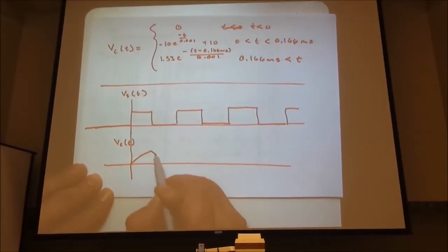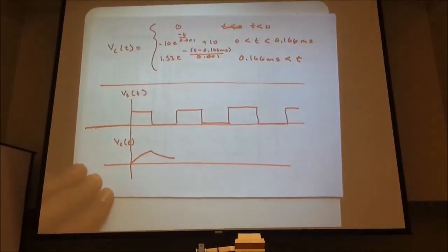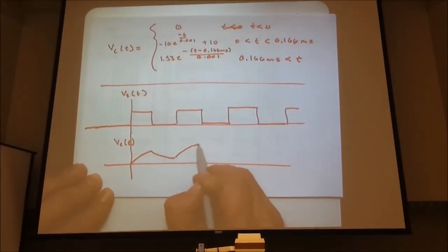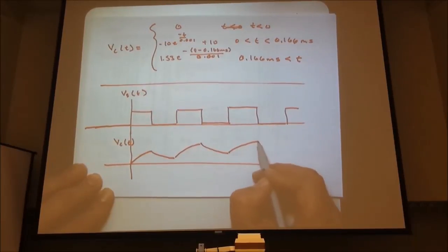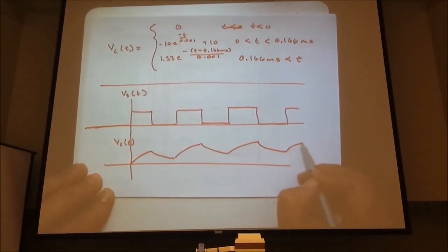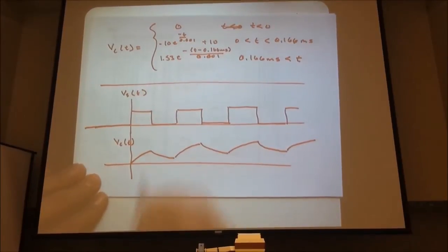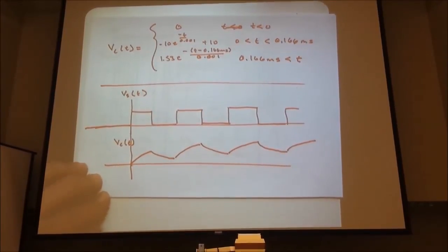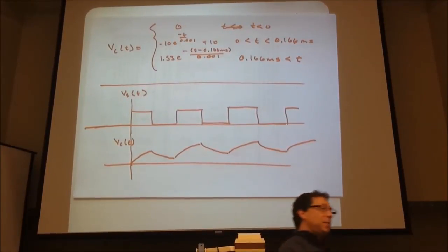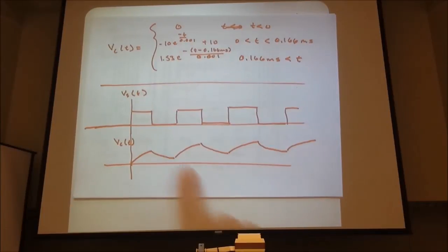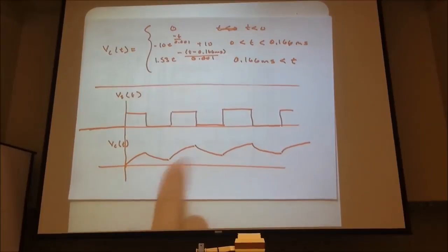So it increases, right? And as it decays here, is it going to decay to 0? No. It decays part way and then charges up. Eventually it reaches kind of a steady state where the decay and the rise are equal. But we start at 0, decay, and climb up until it does reach some sort of periodic function. And this comes back to what I said about turning on sinusoids. So we have some initial transient here. Sinusoids is more dangerous. When we look at second order circuits, we'll see that. So this is a similar type of effect.